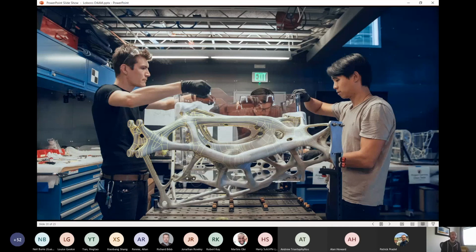Now, if we look at the body of this, most people look at this and automatically assume that this was additively manufactured. It wasn't. It was sand cast. So there's a few interesting points about that. The first thing is that additive manufacturing, particularly in the aerospace industry, you have difficulty proving out the process and repeatability, etc. And there is a natural aversion to these things because of the unknown. Effectively, additive manufacture opens yourself up, particularly with metal additive, to lack of fusion defects, voids within the material, etc.